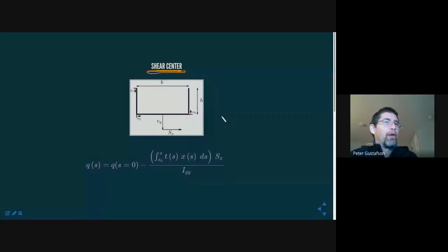All of those have relatively high stability margins. And of course, as a pilot, I am very diligent about loading within the CG envelope for the aircraft. And the way that they would specify the CG envelope for any of these aircraft that I fly, you would not be permitted to load in that region, I'm guessing, because that would be sort of uncomfortable and perhaps unsafe. So that's a long answer to a short question. My answer is no, I've never actually experienced it and can't describe it to you.